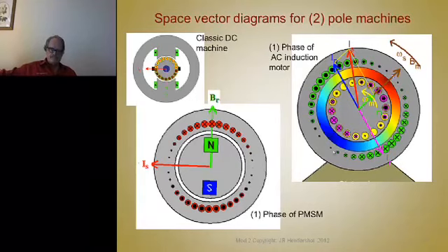And you notice here, what's interesting is you see these currents flowing into the screen and out of the screen. And the rotor current is flowing into these bars and out these bars, you see? And those are 90 degrees approximately, not exactly. See, this is not 90 degrees. But normally it's 90 degrees. In synchronous machines, the current is 90 degrees to the B field, but in an induction motor, it's a little less because of the slip.